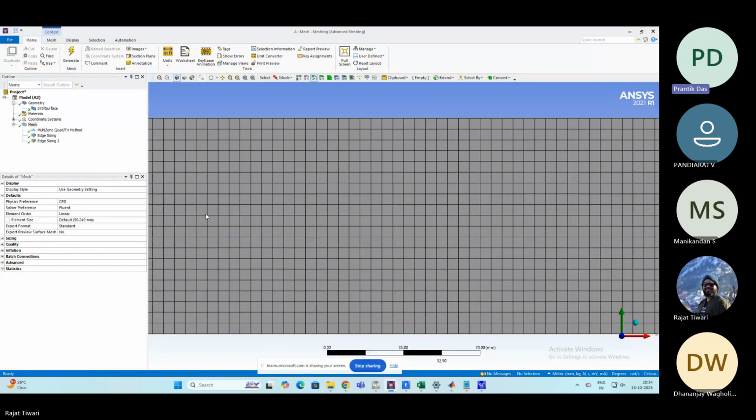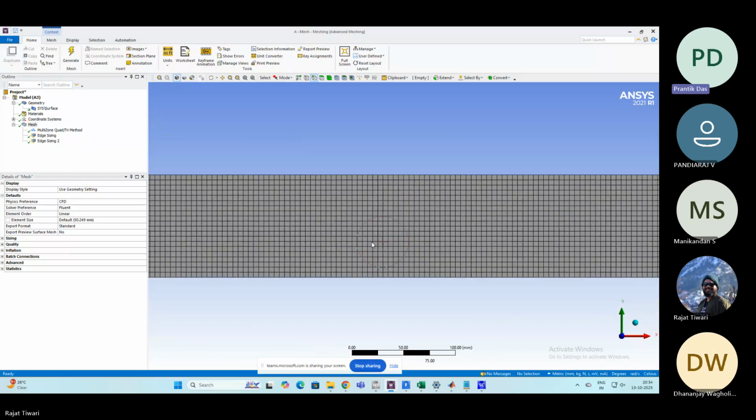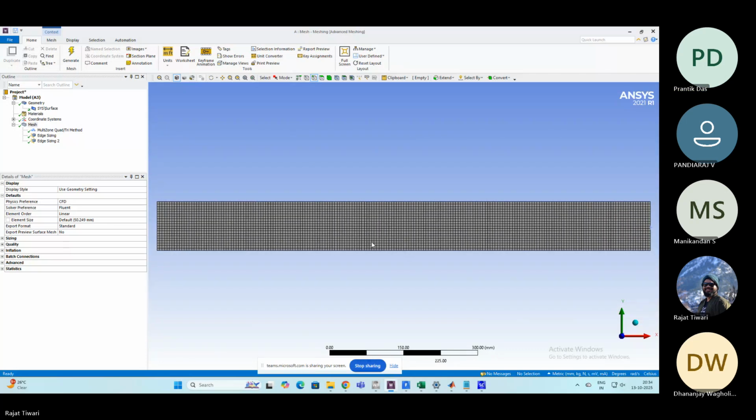So I have to go for a certain kind of mesh resolution in order to capture the flow physics. So I've said earlier that near the cell faces, near the walls also, you have to go for grid refinement, which is called biasing. So as of now, the grid itself is sufficiently fine to go for a uniform mesh. Biasing itself is not required, but if the mesh is not so fine, we have to go for biasing. So this kind of thing actually comes with experience. So is it clear up till now? Yes, sir.